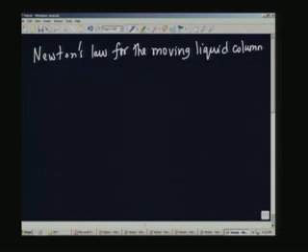This is the force balance. So, I have A L rho m d squared h by d t squared. This is the net acceleration force. This must be equal to the positives minus the negatives.